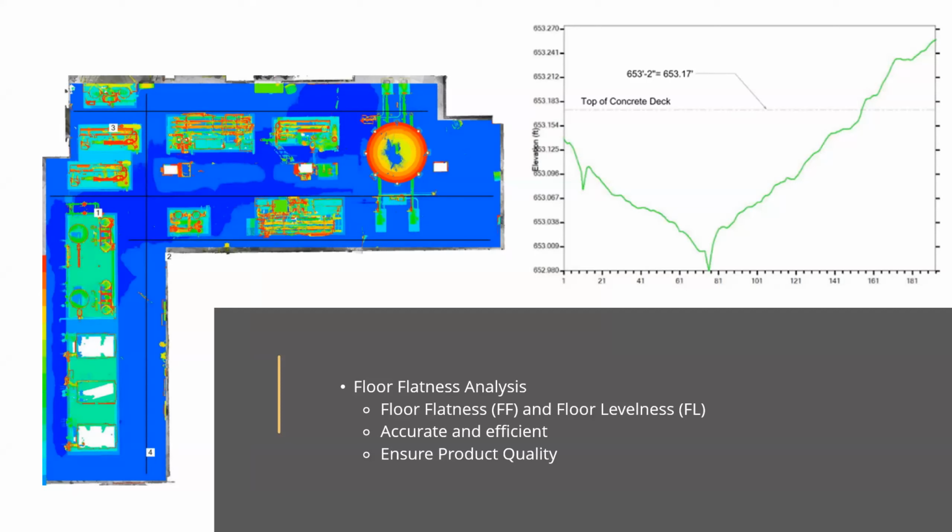One use case on this biotech project was to help the superintendent establish the benchmark point for new housekeeping pads. As you can see from the heat map, the different blues indicate the elevation difference of the floor. The existing floor was built in slope for proper drainage. Our scope of work includes 7 housekeeping pads for new equipment. The client wanted the top elevation of all the new pads to be the same.